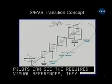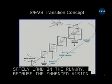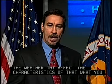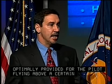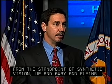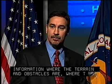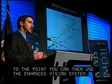But again, because the enhanced vision system is not weather immune, weather may affect the characteristics of what you see. Synthetic vision is optimally provided for the pilot flying above a certain altitude. Synthetic vision, when you're up and away and flying, is weather independent. So you provide the pilots that intuitive and obvious information of where the terrain, where the obstacles are, where the flight path is, to get you set up to the point where you can then use the enhanced vision system effectively. And we use what we call a transition phase to provide visual momentum.